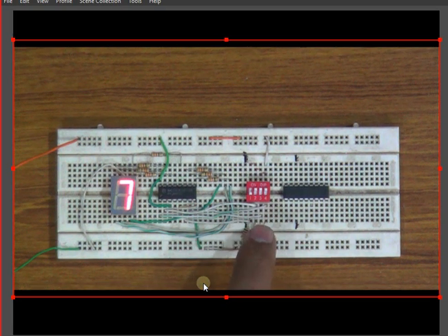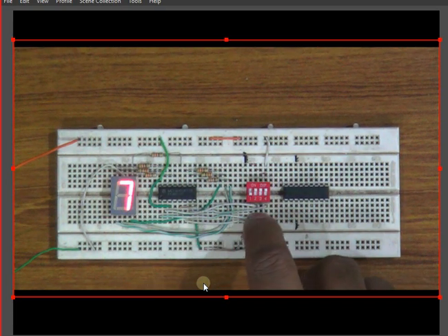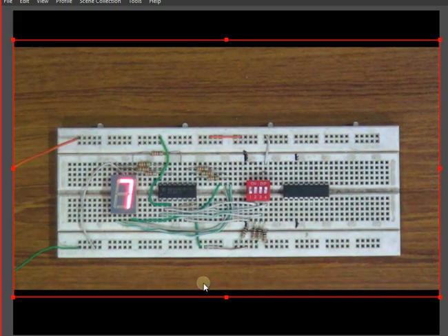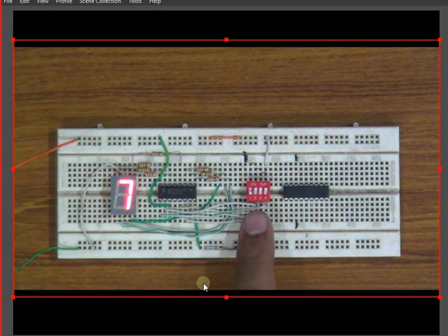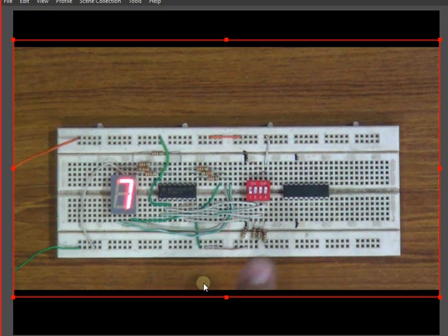You are going to place a male header here, and this data is going to be given through 4 digital wires coming from some microcontroller. So this 4-bit data which is being provided by this dip switch is going to be provided by 4 digital wires coming from maybe a computer, a microprocessor or a microcontroller. So you can display anything on the 7 segment over there.